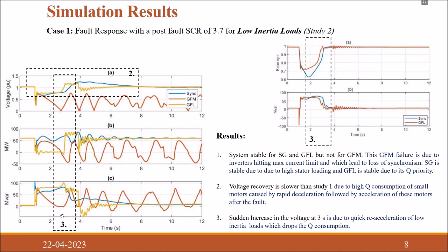The third result which we see is that at 3 seconds there is a certain increase in the voltage recovery, there is a certain increase in the active power injection of GFL, as well as a certain dip in the reactive power injection of the GFL. And this is because there is a quick re-acceleration of low inertia loads, which actually drops the Q-curve.